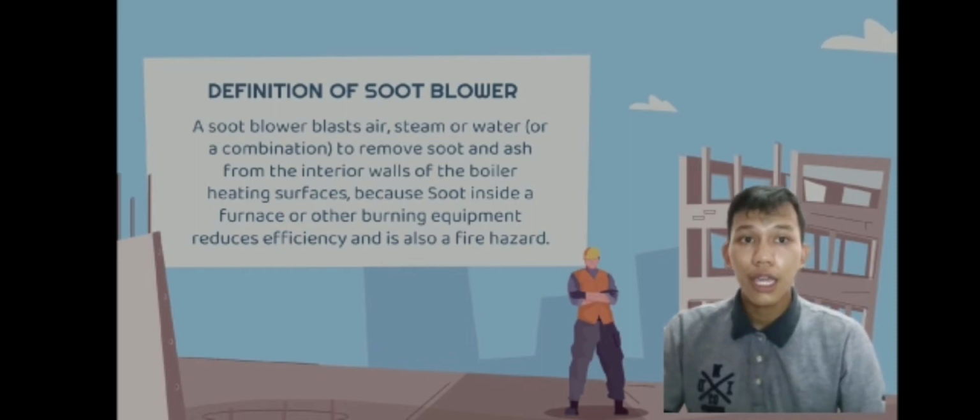Next, soot blowers can minimize the risk of a soot fire. A fire can cause hotspots to appear in the furnace tubes, which can reach a temperature that weakens the structural integrity of the tubes. The dangers and potential damage of a weakened furnace structure are extreme.